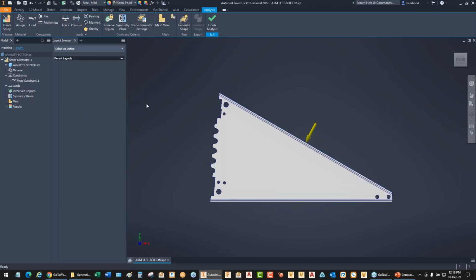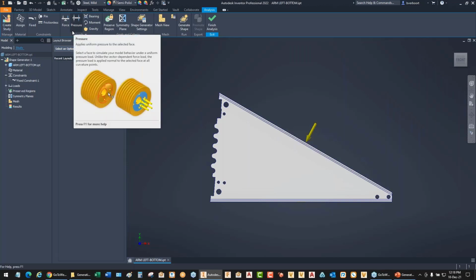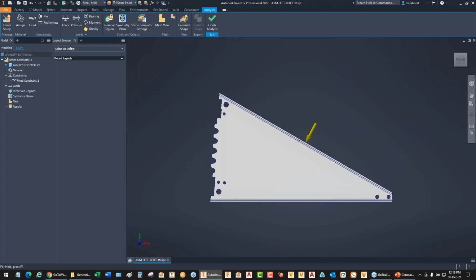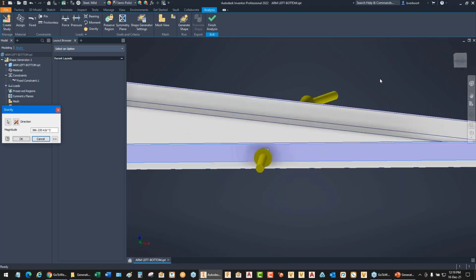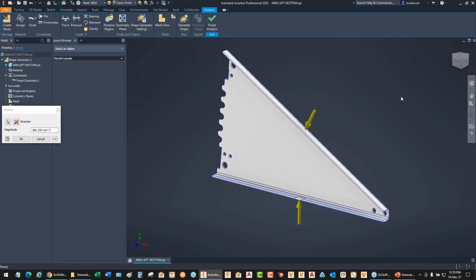Okay, with force applied and a fix on the geometry itself, we can then move forward and we can do additional forces. In this case, we'll keep things very simple. That's part of the title for our event today. So I'm going to move forward, and we're just going to simply add gravity at this point. And gravity is a thing. It is a force. It acts on something around us. And they've preloaded or predefined the gravity force, so we don't have to remember the value for gravity. It's going to be simply asking us for a location to apply that gravity, and then we use the same face that we use to fix or support this particular design.